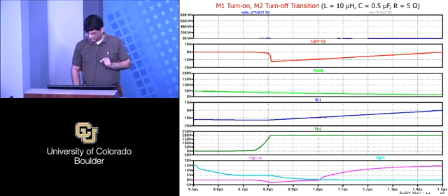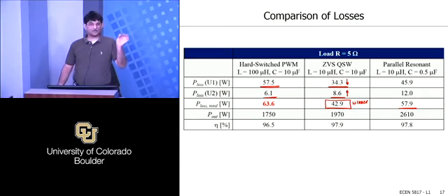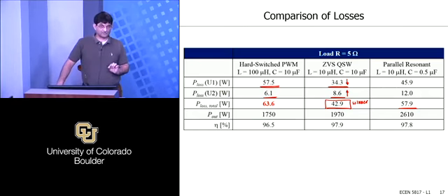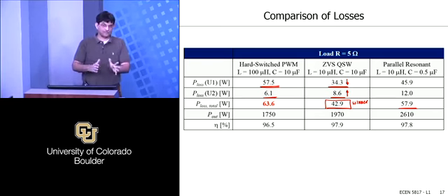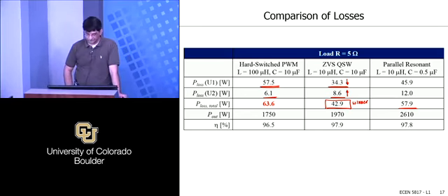And that other factor is that the losses at turn off of these devices are now happening at higher current, again because of the higher ripple, right? So the device has to turn off a larger amount of current, and as we will see, how much current you turn off also determines how much switching loss you will have, right? I mean, we know it's reduced, but it doesn't go to zero, and the amount depends on the current that you have to turn off. So that's the other thing that's going on.